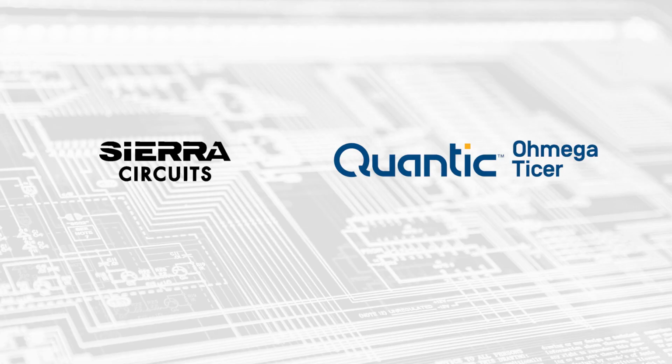People are using very precise things, like laser direct imaging and very good registration. So you may only have a 1 mil tolerance in placement, but that has to be accounted for. That's why you may want to make the electrodes a little bit bigger than the resistor area, just to make sure the resistor area doesn't go outside of that and affect the resistance value. And again, the bigger the better. We have people using 5 mil wide resistors in certain applications, but that will increase your tolerance. So if you can stay above 10 mils, 20 mils as a width and a length, that typically gets your tolerances much better.